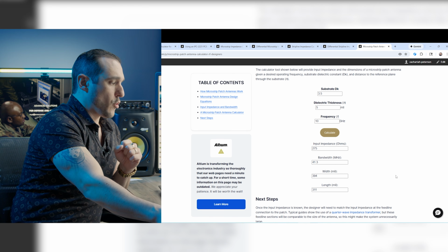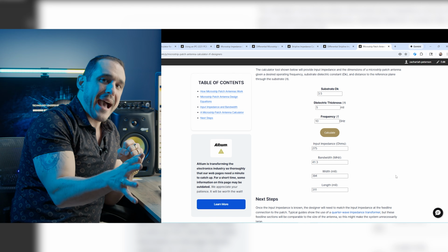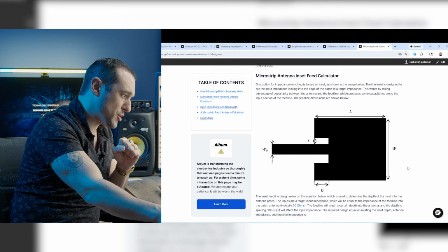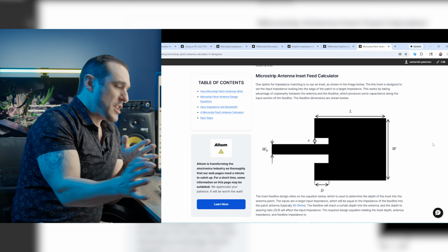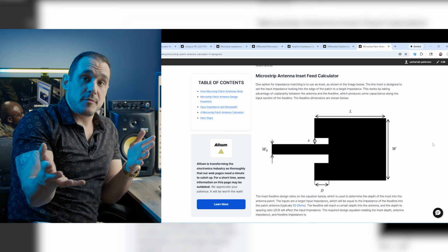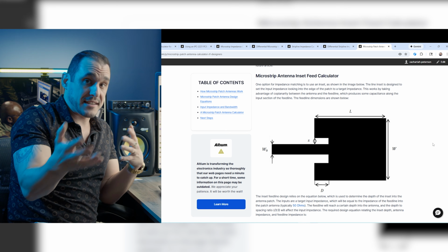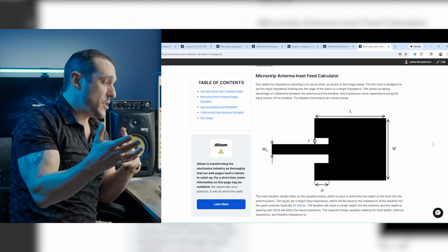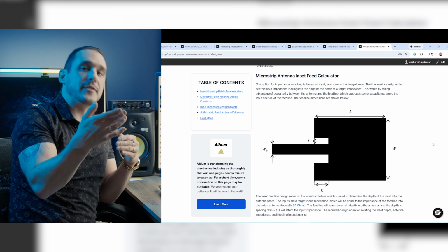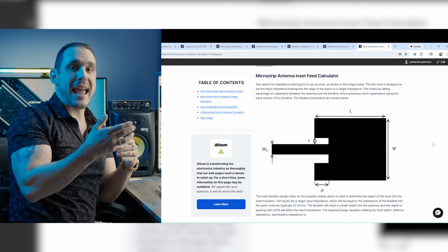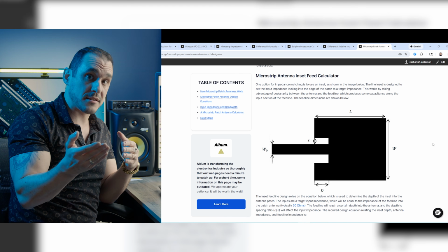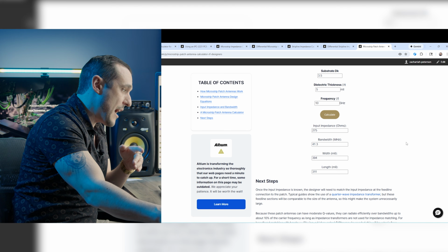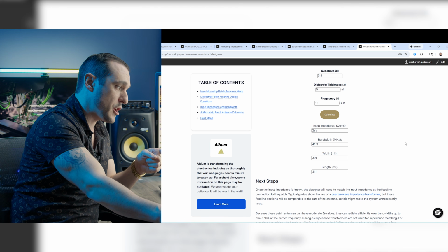Now, oftentimes, in order to get a feed line into a patch antenna, you will actually inset the feed line just a little bit, as shown in this image. Now, typically your feed line is going to be 50 ohms because the component that is broadcasting that signal is probably also set to match to 50 ohms. So you then need to have a match between the 50 ohm feed line coming into the patch antenna and the patch antenna's input impedance of typically a high impedance value, such as the 275 ohm input impedance that we calculated here for this example.